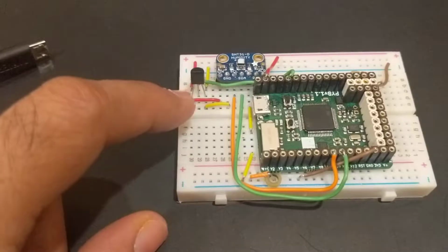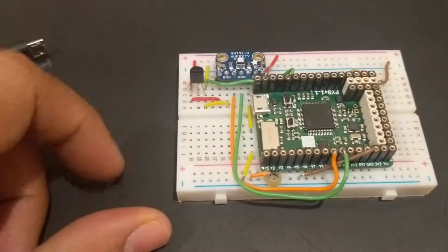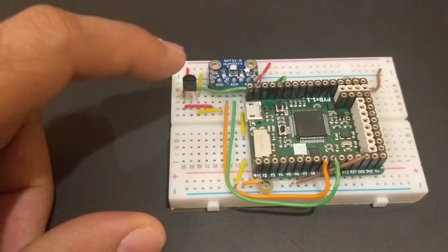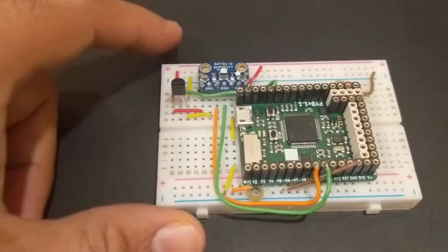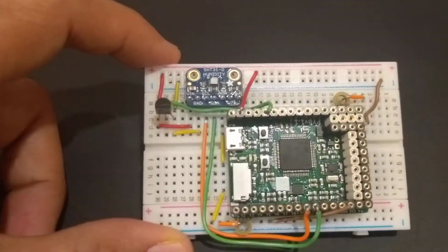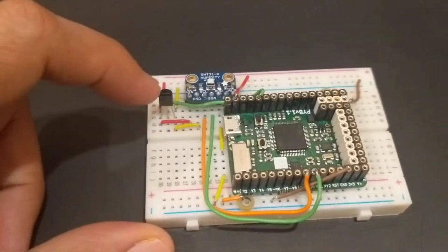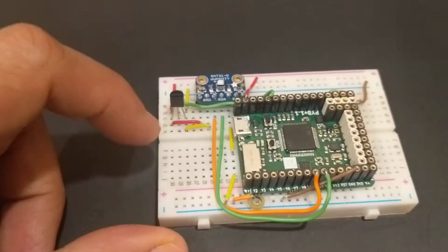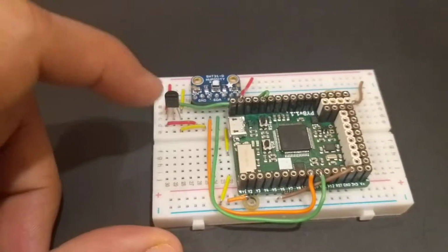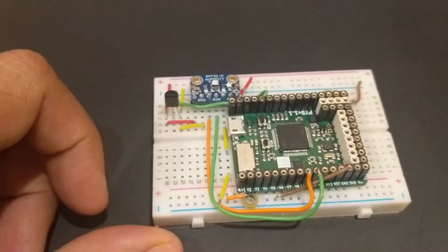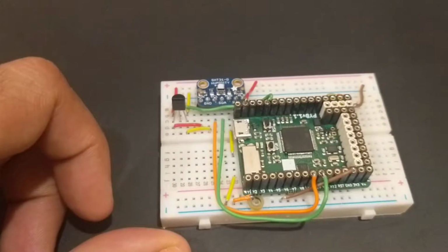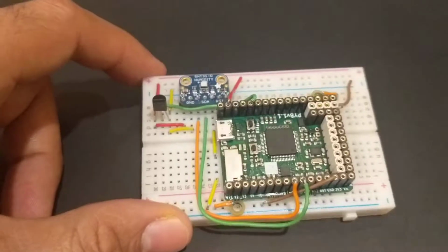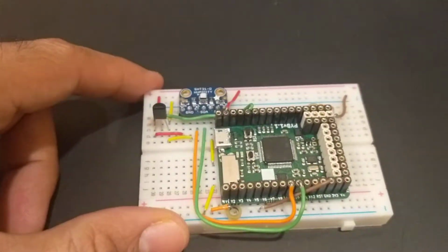Today we are looking at a setup where we use a microcontroller to read temperature data from two different sensors. One of them is a TMP36 by Analog Devices, the other one is SHT31 by Sensirion. The TMP36 is an analog sensor, so we just read the output voltage and then convert that to a digital value,